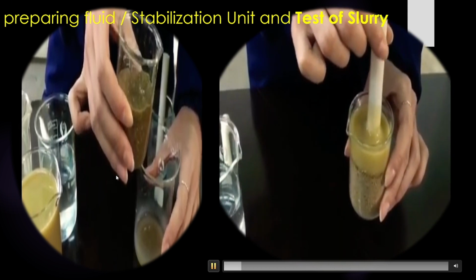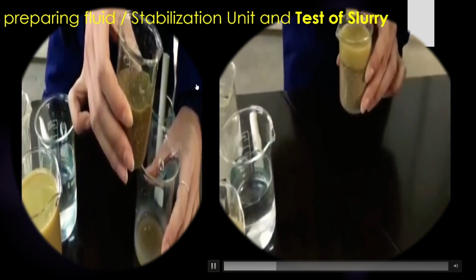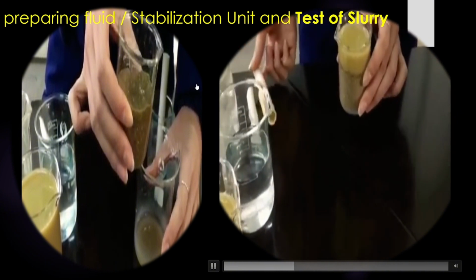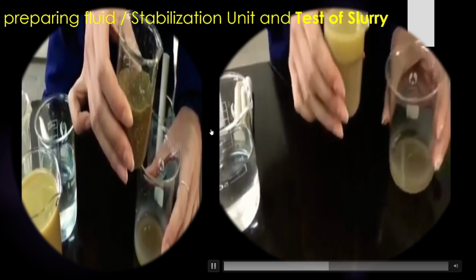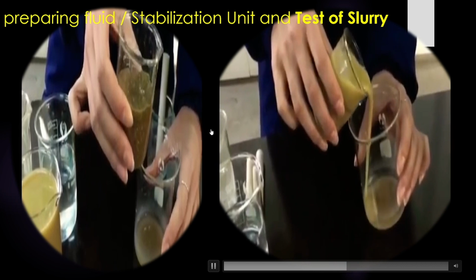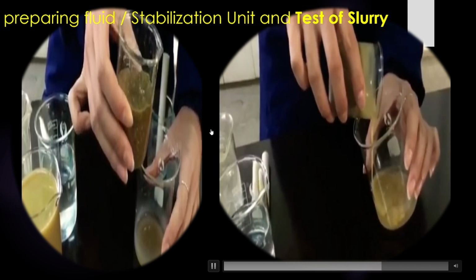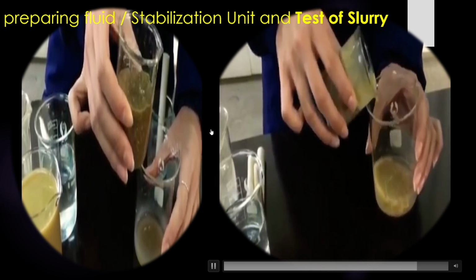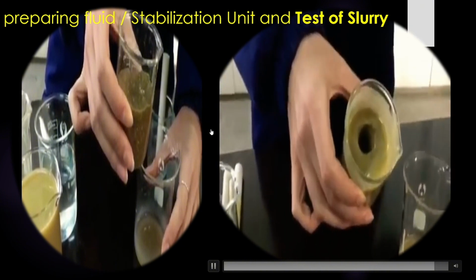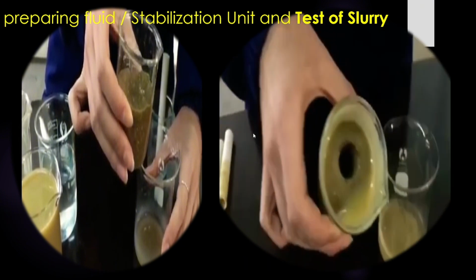As you can see, this is a slurry material at the top, and this is the pile. Then what we are going to do is pump out all the slurry material from the soil stratum, so that the sides of the bored pile keep their own shape, so that we can do the piling concrete and reinforcement caging. As you can see in the figure, it is clear.